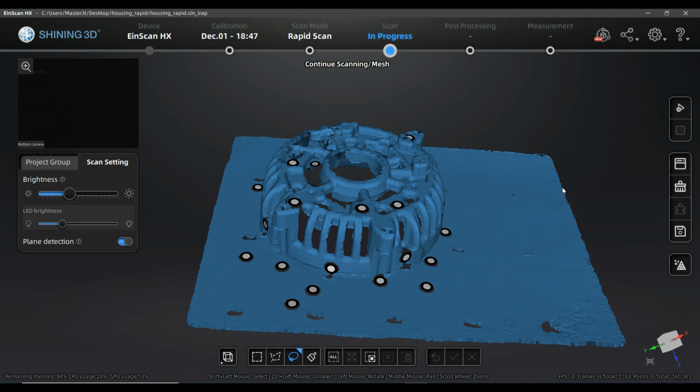Of course, everything that comes afterwards is again the same. If you create views over laser scan or over rapid scan, it doesn't make a difference. Afterwards you go to the alignment if you have a top and a downside and the side that you capture, like with the laser scanner, turned 90 degrees, and you merge them and create an STL model also.